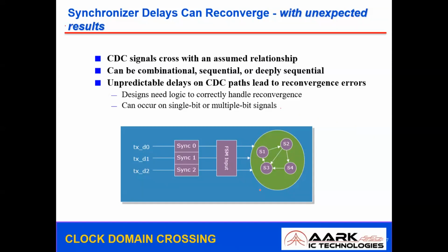Earlier, when we started our discussion, it was a completely unpredictable system. Now, by adding synchronizers, we have prolonged it to a few more years. So the probability of occurrence of these issues has reduced because of the synchronizers. And since these synchronizers add delays, it might lead to some other problems. These problems can be rectified through the reconvergence technique. This can be generated through some control FSMs.